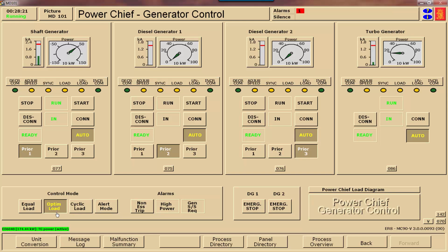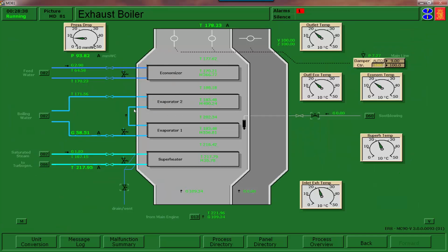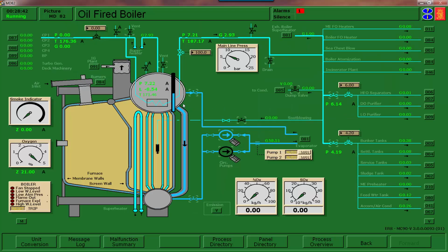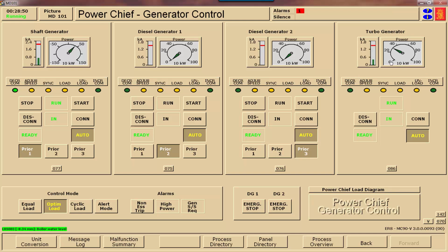The optimal load is designed in the automation so that it will control boiler pressure. Since this is waste heat, right? That boiler is cycled off. There is no fire. The heat for the boiler is coming specifically through the circ pump to your evaporator tubes on the waste heat boiler and back into the steam drum. So this boiler is being fired solely off of waste heat from the main engine. So this is a combined cycle and we are utilizing waste heat.